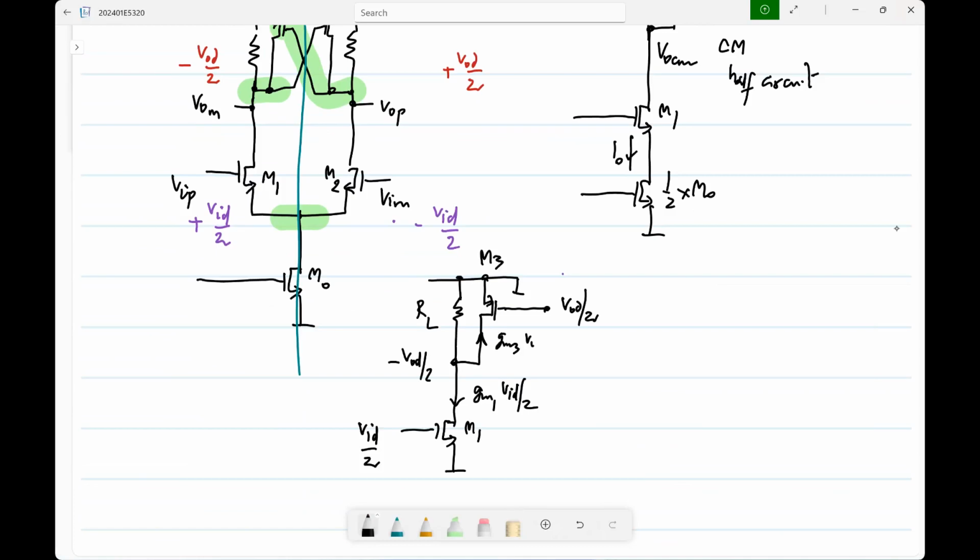GM3 VOD by 2. What is the current there? Minus VOD by 2RL. Okay. So now we have GM1 VID by 2 plus GM3 VOD by 2 minus VOD by 2RL to be 0. Okay. So what is VOD by VID?